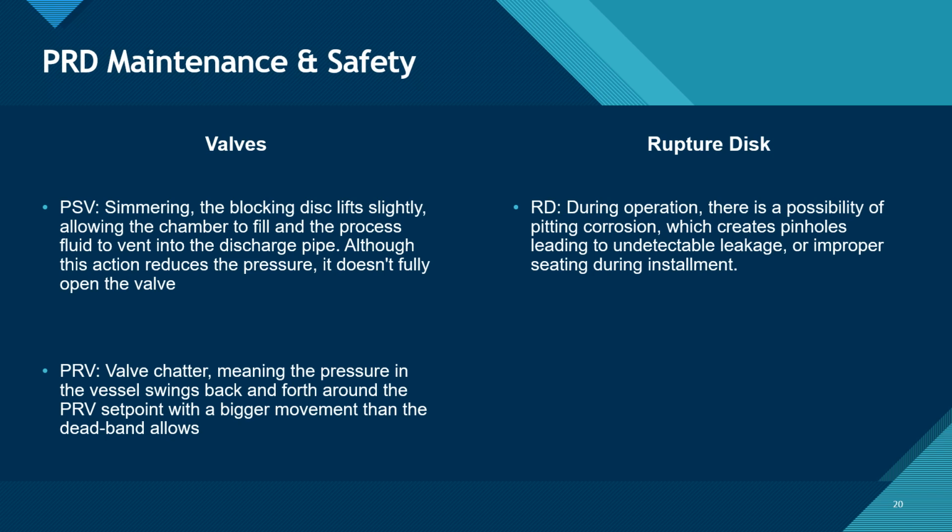Moving on to rupture discs, some of the concerns that we have are during operation, there is a possibility of pitting corrosion, which creates pinholes leading to undetectable leakage. This and or improper seating during installation.